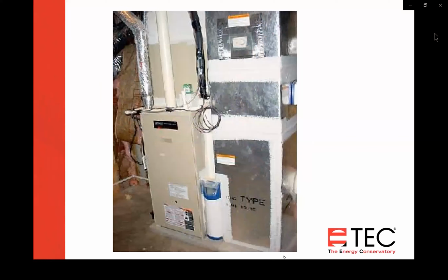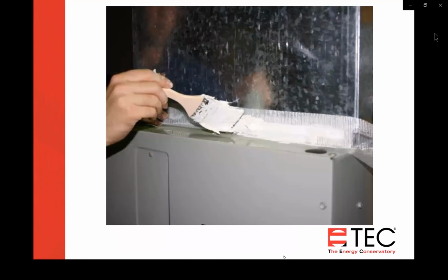If you're using a metal trunk line in an attic, you'll want to test it for duct leaks before you put any insulation around it, for sure, so you can help find the leak. So this is showing duct mastic on all the joints and longitudinal seams. It's showing this being put on with a paintbrush. It's water-based, so a lot of guys will either put gloves on or just grab it with their hands and smear it on. You can certainly use a paintbrush too, but you're not painting it on. You're not putting it on thin like you put on paint. You're putting it on very thick.